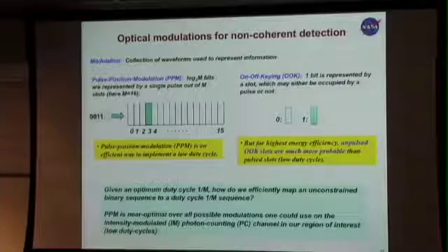So what's the actual modulation scheme we would use? Simplest thing, like I say, is just turn the laser on or turn the laser off in a pulse and put a bit of information that says whether it's on or off. Now, for energy efficiency, you can't make these equally likely. If you make those equally likely, you're back to the same brick wall limits again. The way you get the energy efficiency is to hardly ever use the on pulse. So the probability of the on pulse is very small relative to the probability of the off pulse, because the off pulse doesn't cost you anything.